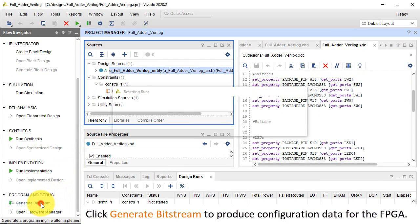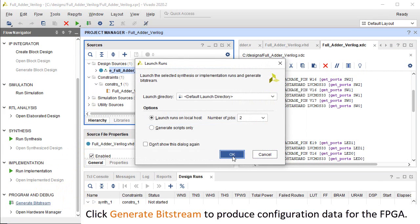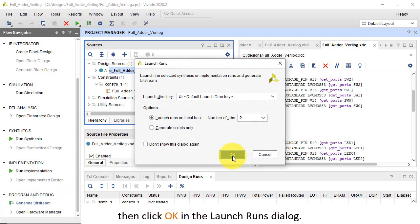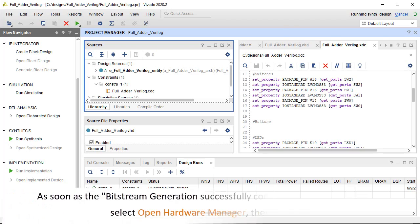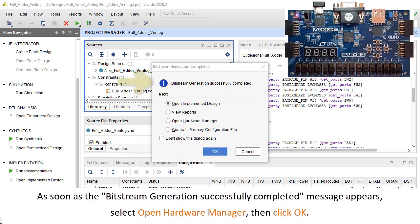Click Generate Bitstream to produce configuration data for the FPGA, then click OK in the Launch Runs dialog. Now connect Basys 3 via USB with the Vivado machine and turn the board on. As soon as the Bitstream Generation Successfully Completed message appears, select Open Hardware Manager, then click OK.